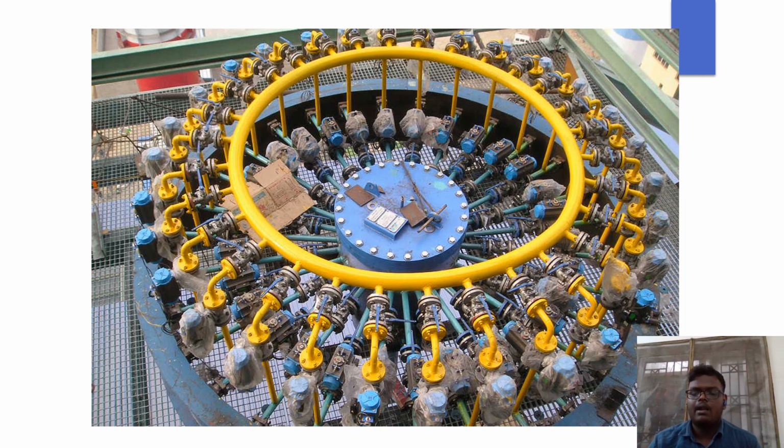The most remarkable aspect of this method is that it allows cheaper coal to be consumed in the system, replacing expensive coke, thereby remarkably cutting down on costs. Because of the severe environment inside the furnace, which is greater than 2000 Kelvin, visual observation of raceway shape and size is impossible. Therefore, remote measuring sensors are used to investigate the chemical and physical reactions inside the furnace.